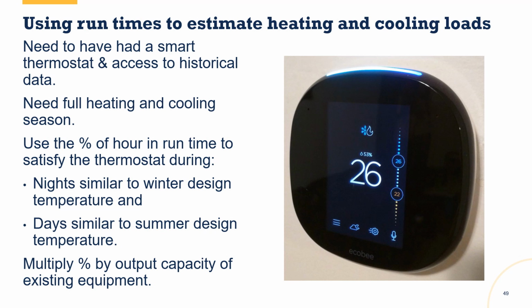If I had an 80,000 BTU system and it was 80% efficient, then I know that 3/4 of the BTUs that went in are what came out, so I know that it's 60,000 BTU out.